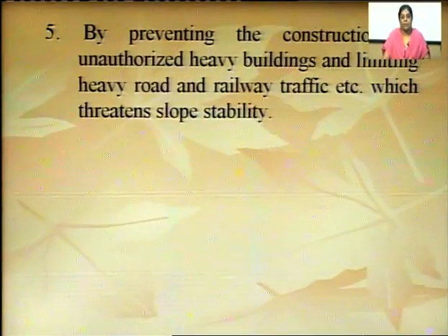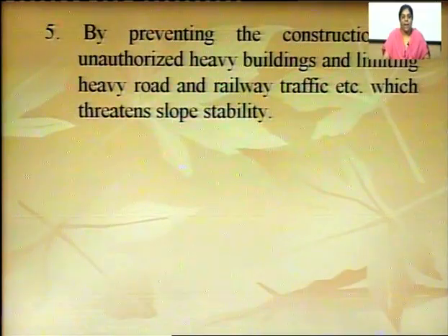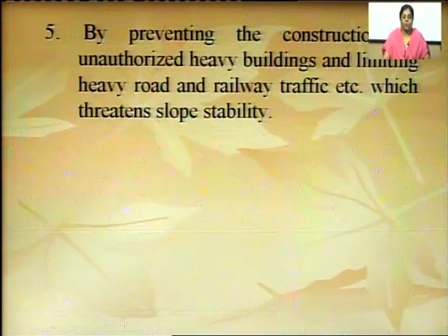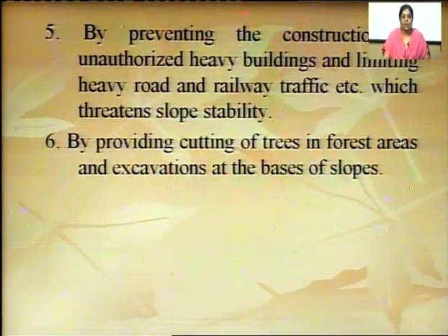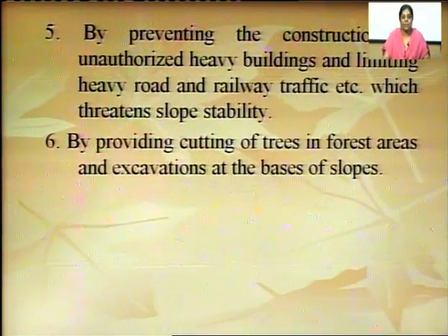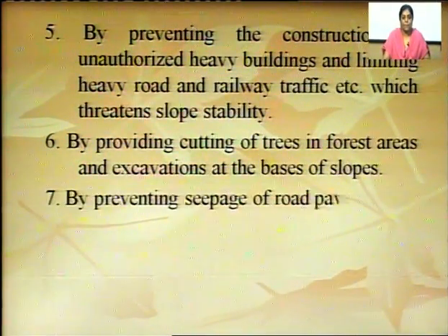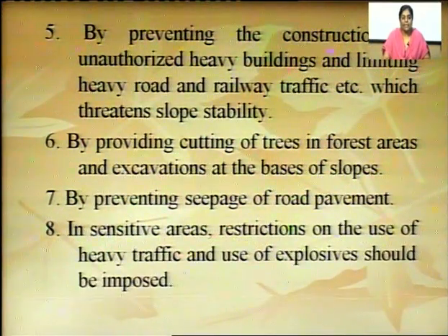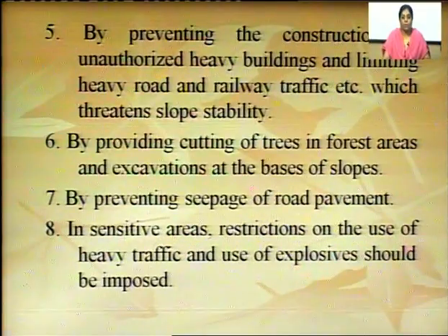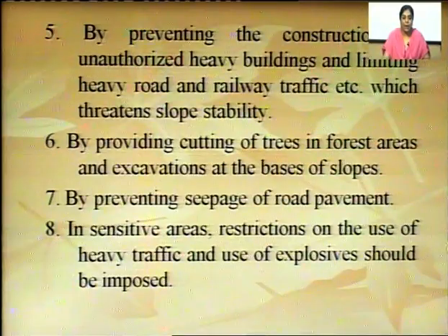By preventing the construction of unauthorized heavy buildings and limiting heavy road and railway traffic, etc., which threaten slope stability. By preventing cutting of trees in forest areas and excavations at the bases of the slopes. By preventing seepage of road pavement. In sensitive areas, restrictions on the use of heavy traffic and use of explosives should be imposed.